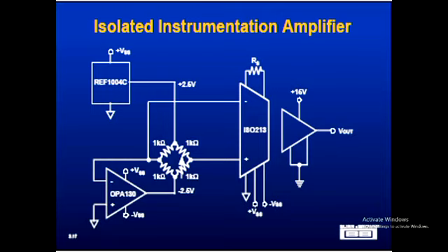And this is the zero line, and we got 2.5 volts coming down from the zero line, correct? This 2.5 volts is plus 2.5 this end compared to minus 2.5 that end. But this end is fixed at 0 volts, so this is below ground level, if you like. Does that make sense?